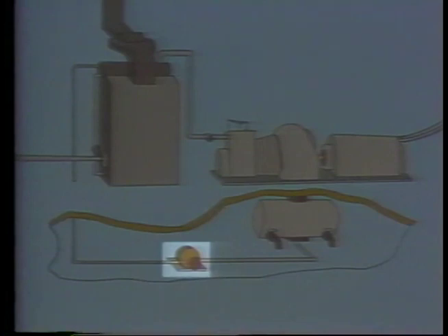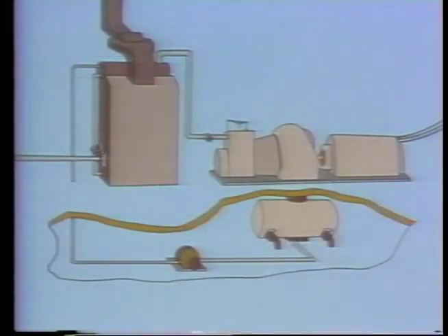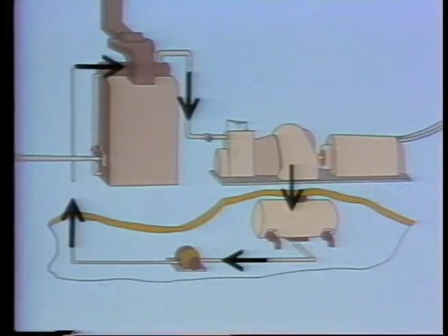Once steam is passed through the turbine blades, it's exhausted into the condenser. The condenser cools the steam, changing it back to water. The condensate, as it is called, drains into the hot well, where it stays until condensate and feed water pumps send it through a piping system that eventually returns it to the boiler. The plant cycle is a closed loop that allows the same water to be used over and over again. Sometimes the water is used in its liquid state, and sometimes it's used in its vapor state, steam.